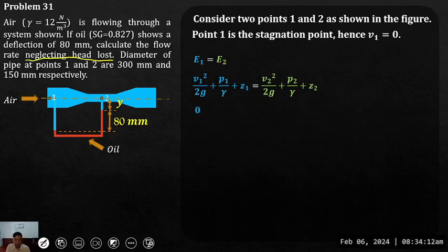Okay, so again, for a pitot tube, we will assume that the velocity at point 1 is 0. Ayan. Plus, yung point 1, since closed na yung ating pitot tube, no? Kinonect natin siya sa piezometer sa point 2. So, ibig sabihin, hindi na yan 0. Okay, so P1 over gamma na yan. So, we cannot use no, yung formula na na-derive natin, yung square root of 2GH in this particular example because our tubes are closed.